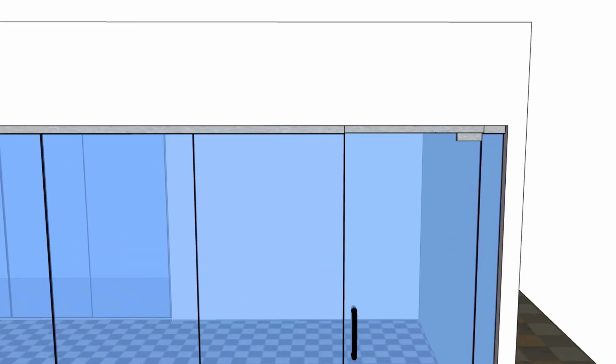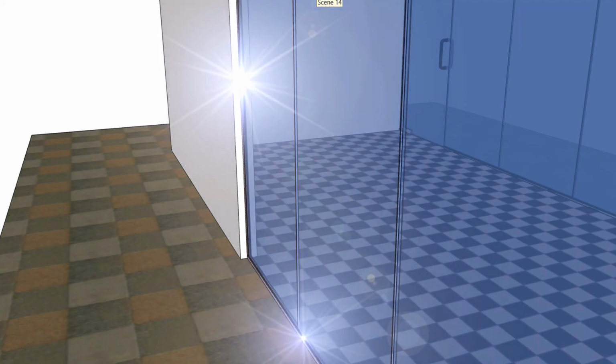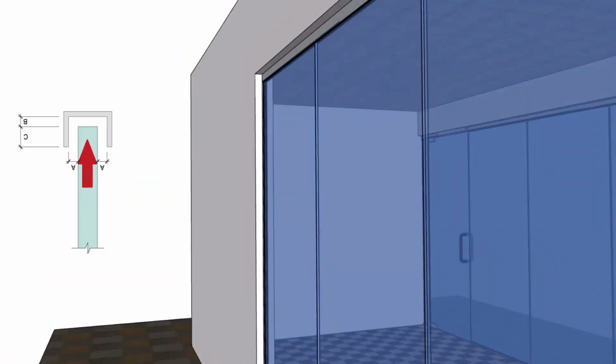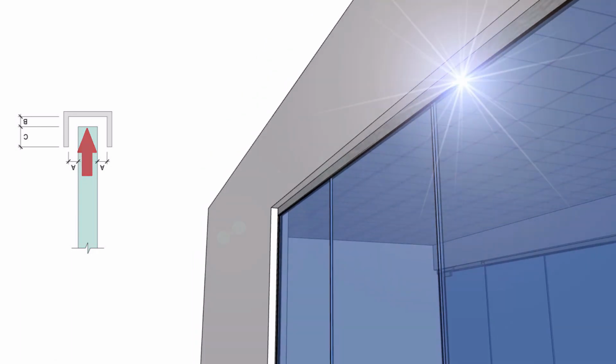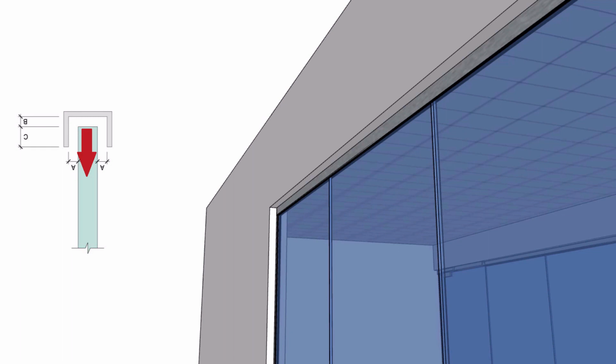Vertical edges between glass panels should be within 1/16 of an inch of parallel, as measured at the top and bottom extremities of the joint. There should not be edge reflection in the finished result. A minimum 1/4 inch of the glass bite into receptors is required to avoid edge reflection. This is critical at the top receptor, where deflection causes the glass to pull out of the receptor.